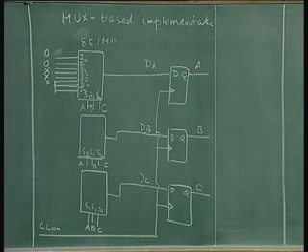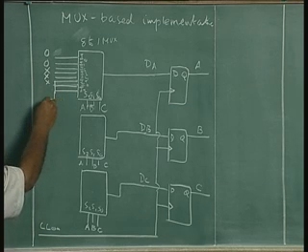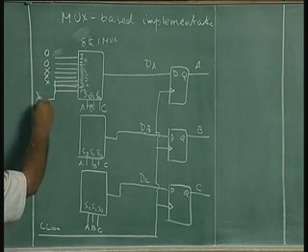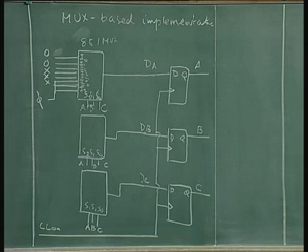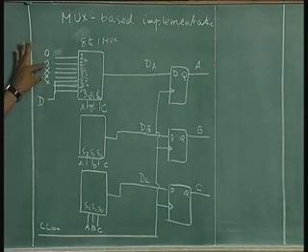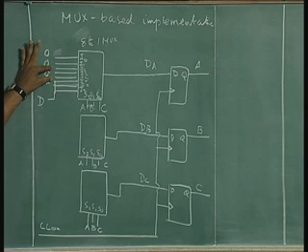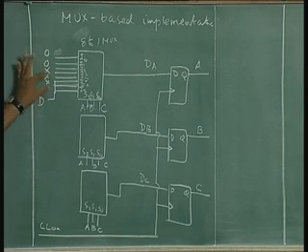Isn't it? So, don't cares, don't confuse this, don't cares. So, I will put a D or a phi here. You know, some people use phi in don't care state. Some people put a 0 there. 0 should not be put because you have a 0 logic. So, I will put a D also if you want. X is used, but since I already used it as X variable, I want to use it as a D, don't care variable. So, first 2 inputs have to be tied to 0, next 3 inputs have to be tied to the input X, and the last 3 inputs can be tied to anything, it can be 1 or a 0.